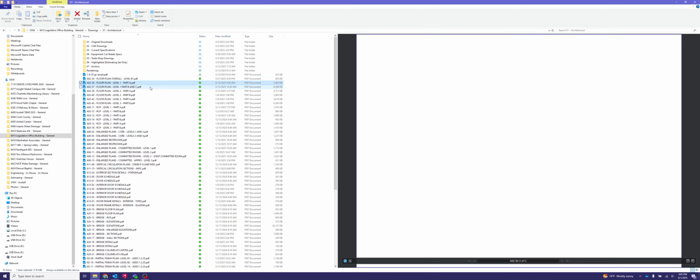Quick note too, anytime you have a finished end, make sure that that countertop overhangs the edge of the cabinet by 1/4 of an inch. That is really important. We'll definitely be drawing that in here shortly.